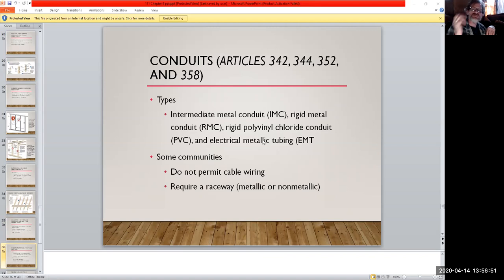And then we get into, and it depends, you might run into situations where the residential homeowner wanted you to run conduit, which, if you're not used to dealing with it on a regular basis, is a lot of fun because now you've got to make all these bends you're not used to doing. There are also commercial situations, and always, always, always in industrial settings. You will not see sheathed non-metallic cable used in an industrial setting. I'm pretty sure it's not allowed.